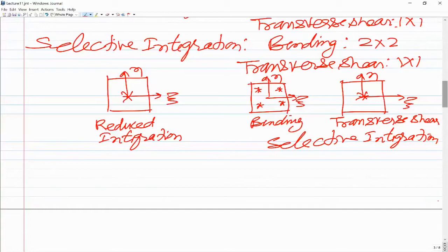Now if we evaluate the transverse shear strain only at the center point, that is xi equal to 0, eta equal to 0, that would be a constant term, and the constant term has contributions from W as well as theta x or theta y. So that does not lead to spurious constraints. That is how it eliminates the locking.